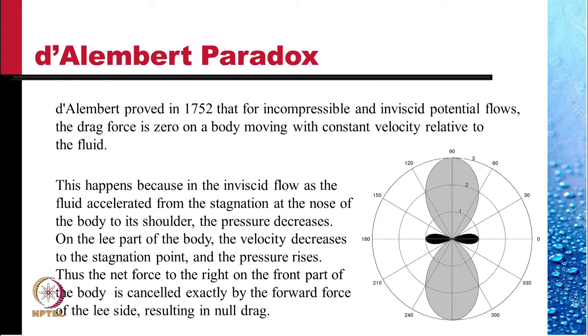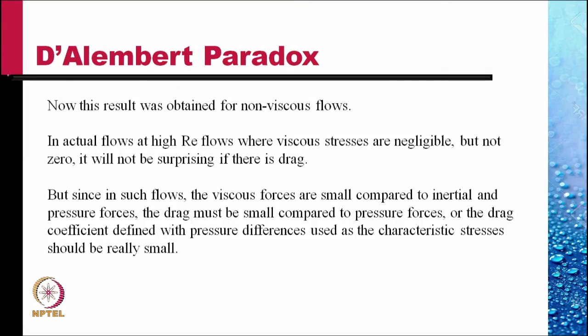It was proved later that this drag is 0 on all bodies, whatever be the shape, not necessarily cylindrical or spherical. Now, this result was obtained for non-viscous flows. In actual flows at high Reynolds number, where we have shown that we can neglect viscous stresses, the drag is not 0.